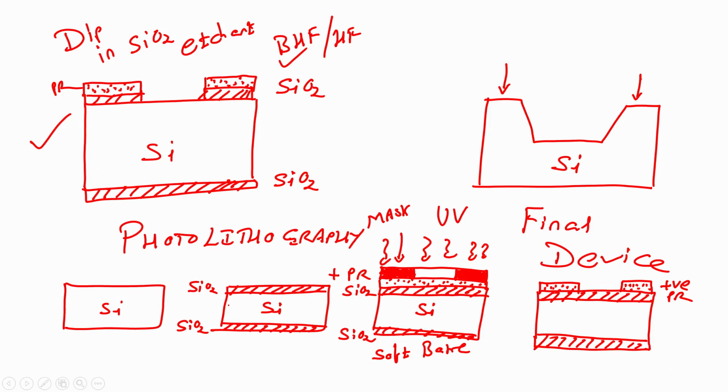And then I can etch the silicon wafer. So, after this I can remove or strip off my photoresist by dipping the wafer in acetone. If I dip the wafer in acetone, then I will be able to strip off the photoresist from the top of the silicon dioxide, and then I will dip this wafer further into silicon etchant.